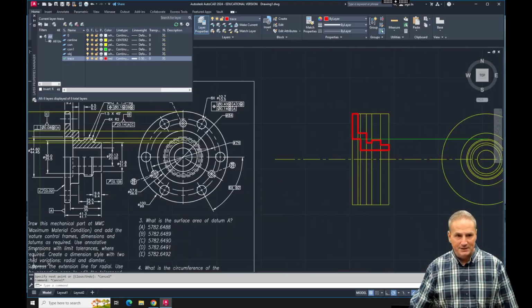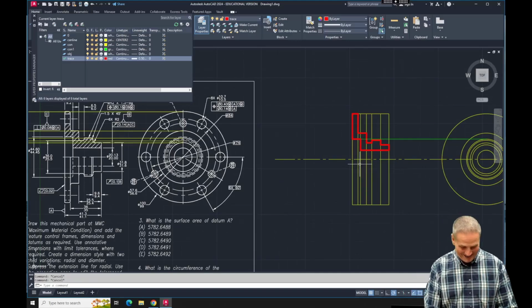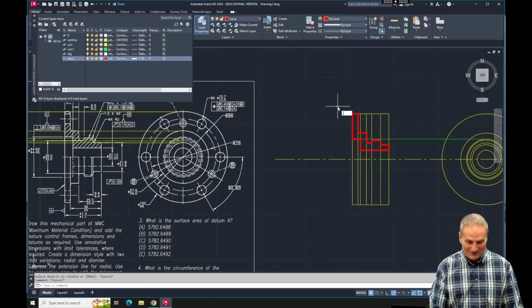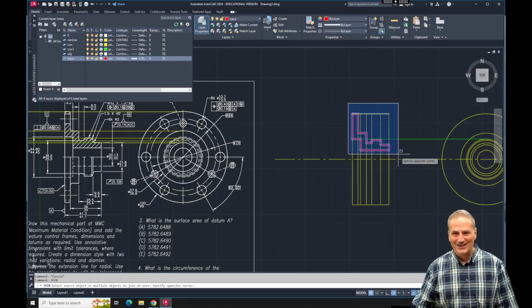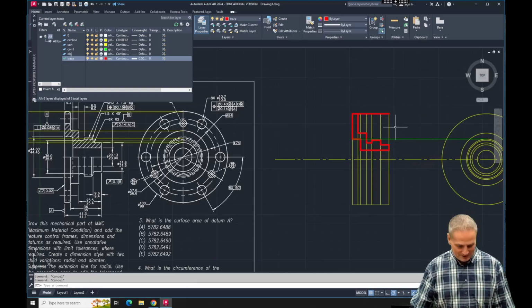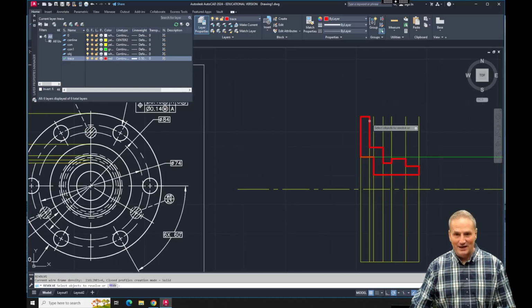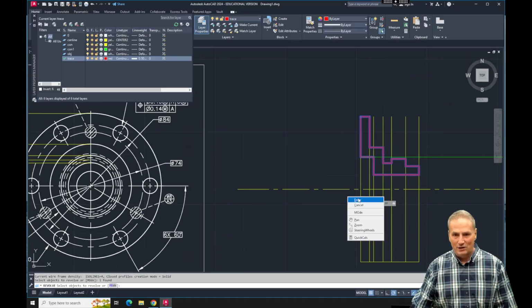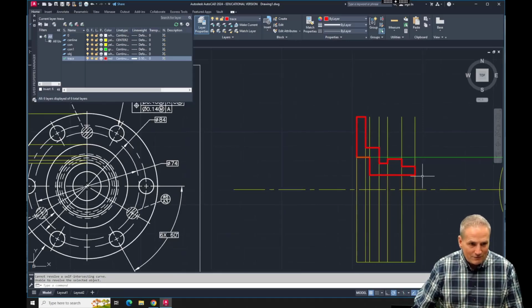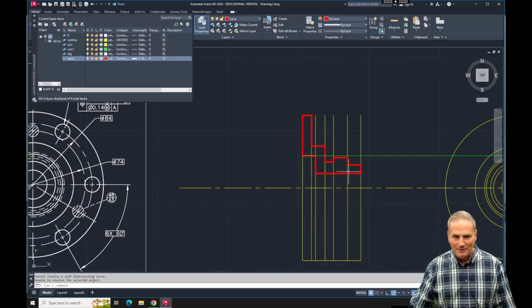Now you've got fillets and things to do here. But eventually, well, you're not going to revolve. It's not 3D class, but you could, right? I mean, for those of you in 3D class also, and some of you are, if I joined all those together, oops, Dan's point about the trim command. Sometimes it can be a little bit of a pain. But if I now revolved all of that around my center line, unable to revolve the selected. I probably have some lines that overlap themselves, I would assume.